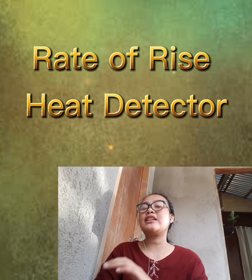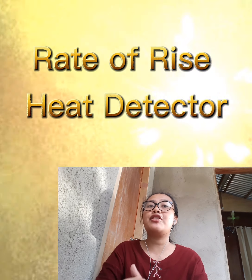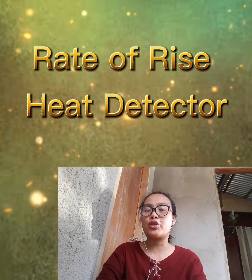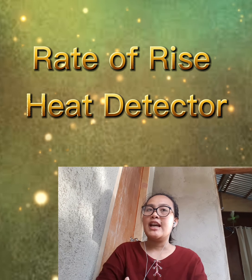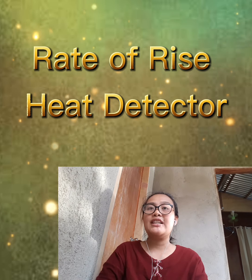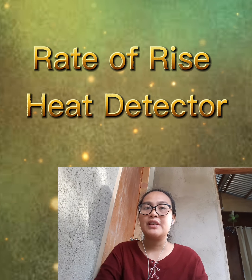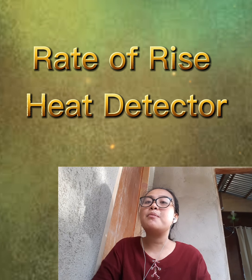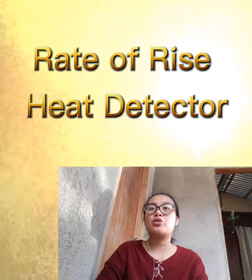Second, the detector shall be provided with a fixed temperature backup feature so that at a lesser rate of rise of temperature, the fixed temperature element shall operate. And also, the detector shall latch in the alarm condition until reset manually. And also, the detector bases shall be suitable for surface or flush mounting as required to suit the area of installation.